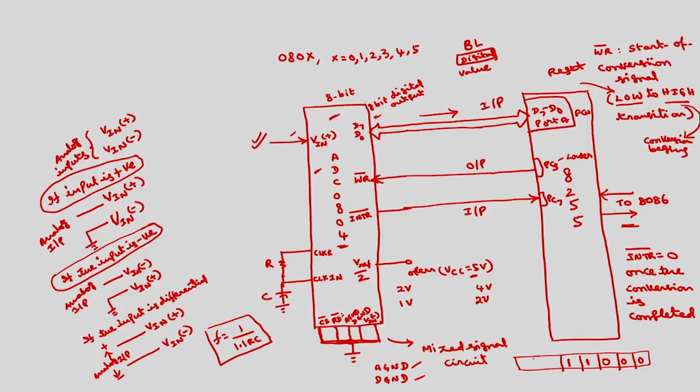Mode selection for port A, I am going to use mode 0, and then this is the mode control signal which is equal to 1. So what is the corresponding hexadecimal? This is 98H. If I enter this 98H into the control register of this 8255 whose address is FFH, then this will set port A as input port through which the data will be read, port C lower as output port, and port C upper as input port. This is the first instruction.